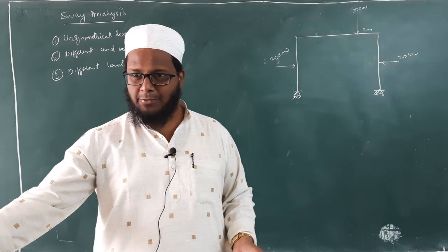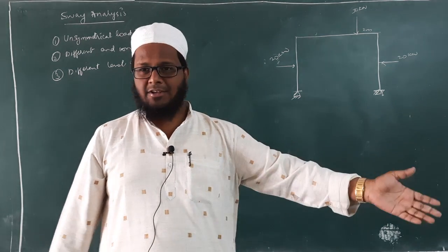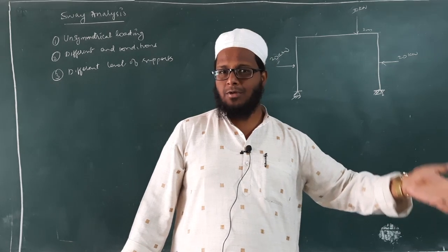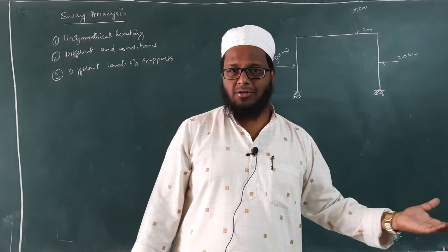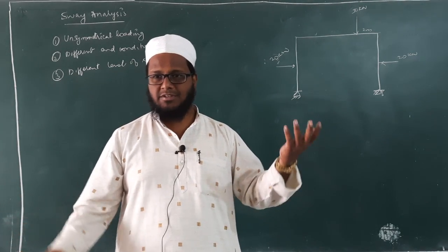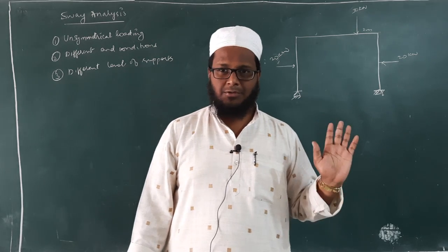Suppose for example you have to go 6 feet or 7 feet, then on the other hand you get a hard stratum at just 4 feet, so you need not go up to 7 feet or 8 feet or 6 feet. So what will happen there? The support conditions are different, isn't it? The level of support is different. Because of different levels of support, it may lead to sway.